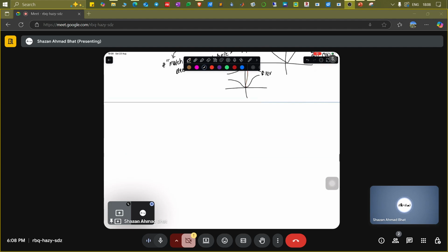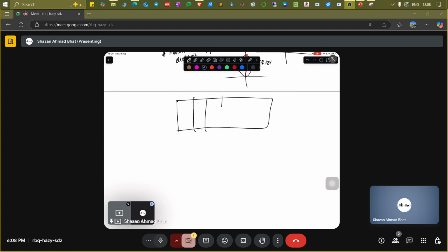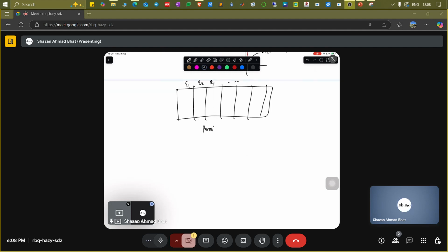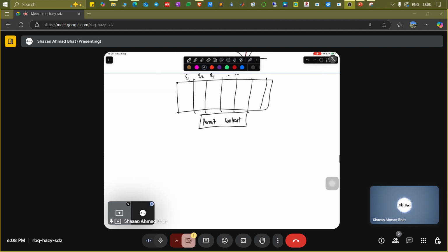Now we are going to see, let's say for example, if you have the permittivity of this as epsilon 1, epsilon 2, epsilon 1, and so on and so forth, there is something called the permittivity contrast. So how much is the variation in the permittivity, and it's given by delta omega over omega, which is delta epsilon by epsilon times sine of pi d over a. So this basically also tells us what the frequency is.